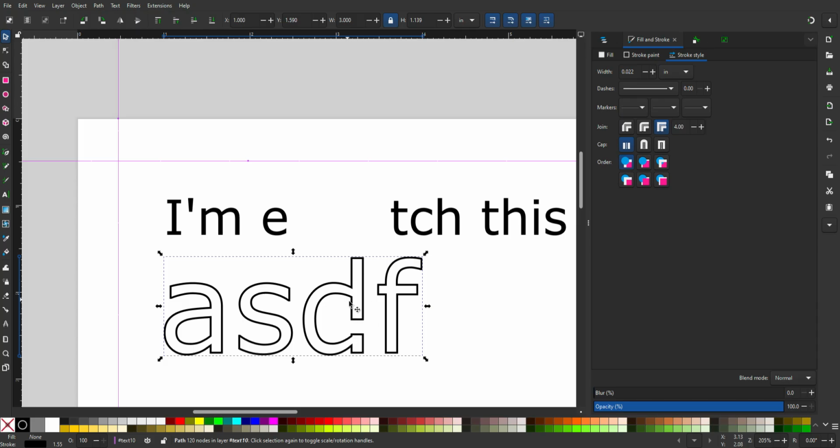So now it's going to cut that D out. It's going to hold that hole there, so it'll still read like a D. And you'll need to worry about whether that hole is big enough so that the laser isn't just cutting it out. If this is too close and your letters are too small, the laser will still cut the whole thing out.